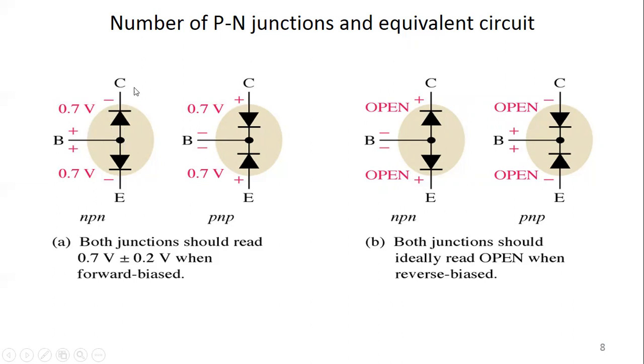as those are diodes, we need to apply the barrier potential across these diodes. The barrier potential for this particular PN junction diode is 0.7 volt, that we have studied in unit number 1.